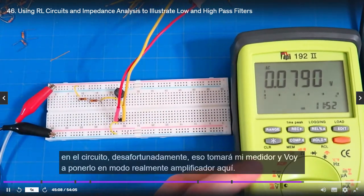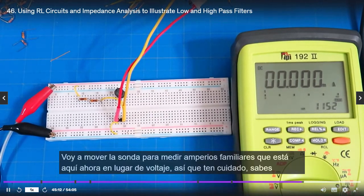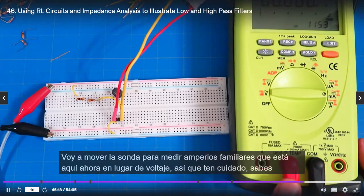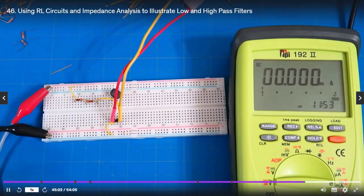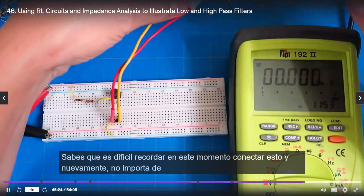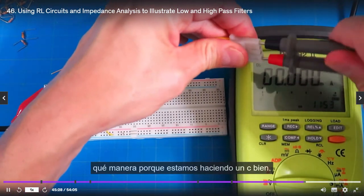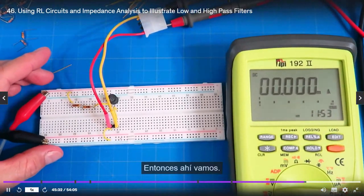Then I'm going to take my meter and put it into milliamp mode here. I'm going to move the probe into measuring for milliamps, which is right here, instead of voltage. So be careful. I make that mistake all the time. It's hard to remember. All right, then I'm going to plug this in. Again, it doesn't matter which way because we're doing AC. I'm going to plug that in nice and tight. Okay, so there we go.